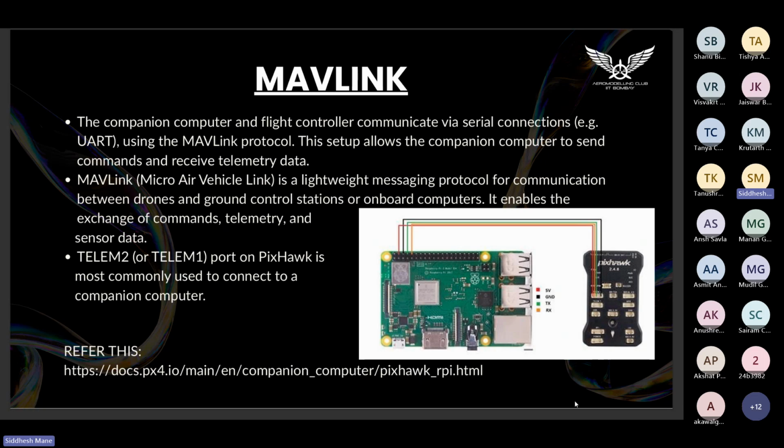Ayush has already talked about MAVLink. So what is MAVLink? MAVLink stands for Micro Air Vehicle Link. It is a messaging protocol used for communication between a flight controller and a flight computer. Also the LiDAR sensors and the onboard cameras use the MAVLink protocol to communicate with the flight computer. So that was about MAVLink.